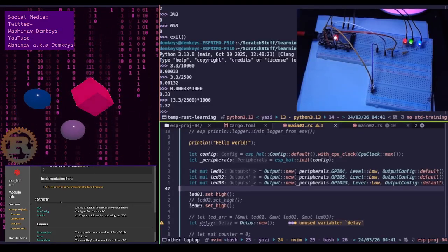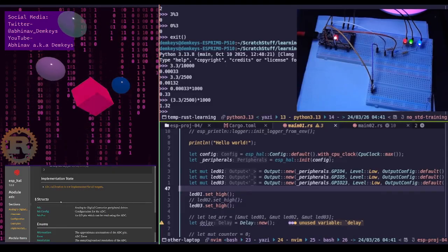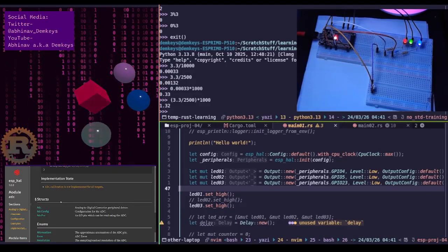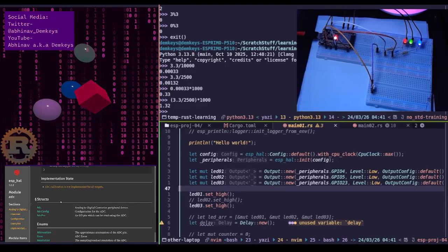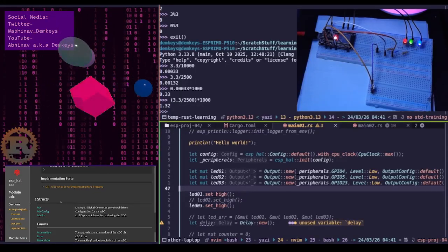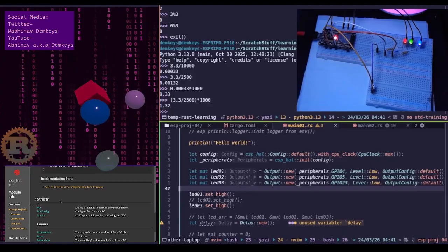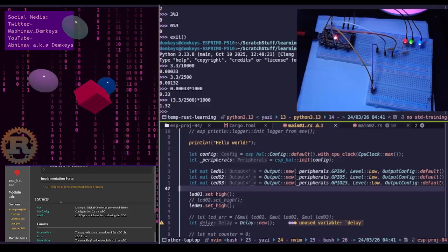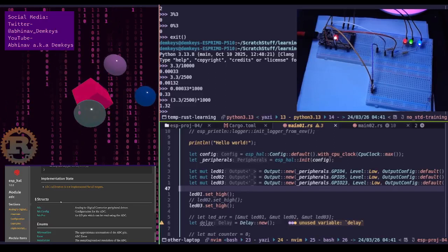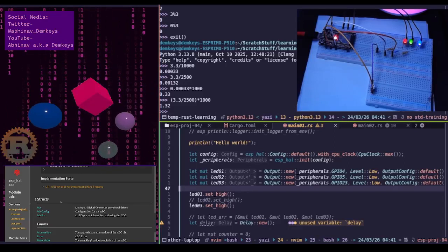Imagine your divider is two 10K ohm resistors giving you 1.65 volts. Okay, so at the center is giving 1.65 volts. If you attach an LED that also has some internal resistance, you have now placed the LED in parallel with the bottom resistor.